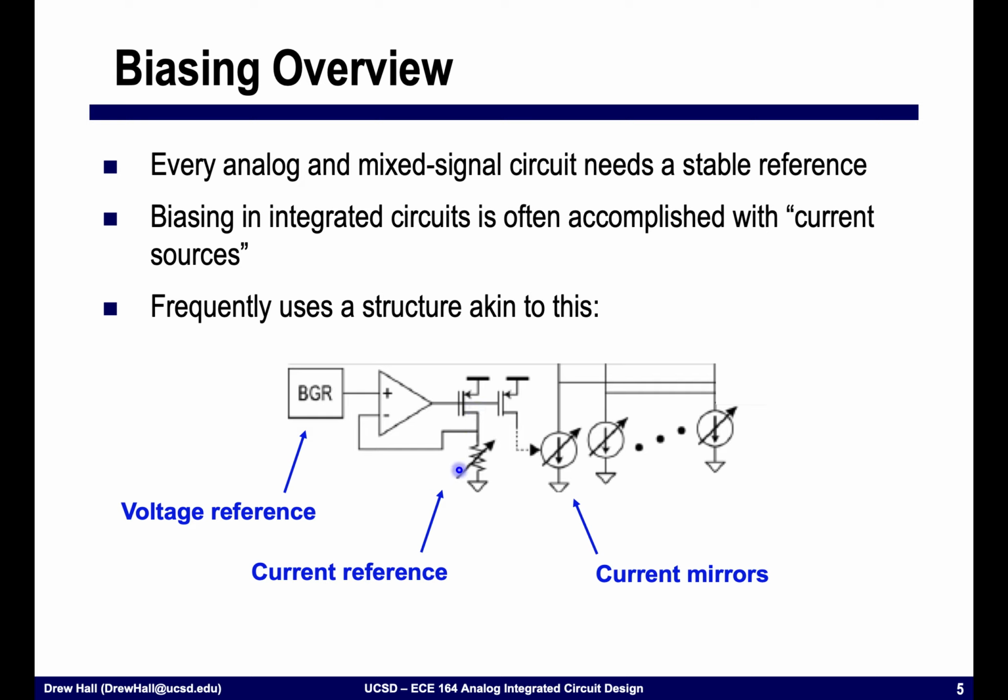What this typically lets you do is that you have an adjustable resistor here where this amplifier is going to force this voltage at this node to be the same as the positive voltage. And so we're essentially dropping V divided by R current over this resistor. And then we're going to copy that current many times such that we generate programmable current references.